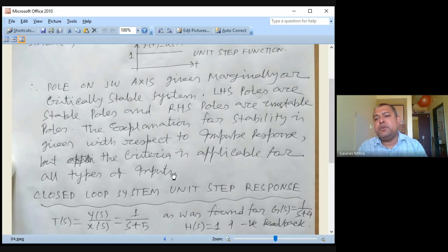And from the impulse response and from the characteristic equation of the transfer function, we try to find out whether the system is stable or unstable through the position of poles. So we solve for the denominator equation. If you find the denominator equation has all poles in the left hand side, we call the system stable. Because poles in the left hand side means it will produce an asymptotic kind of curve in the time domain, and an asymptotic curve has bounded energy, bounded area, and bounded area means the system is stable. So this is the whole story.